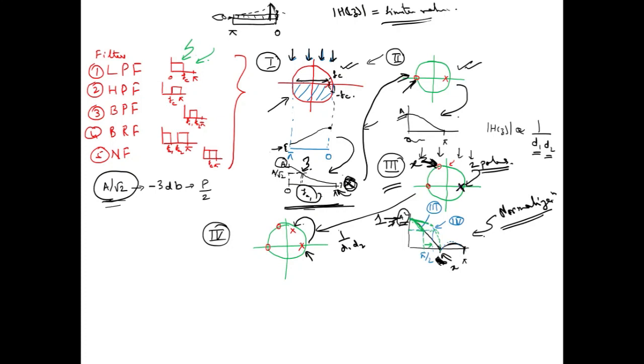So whatever output you get, there will be some frequency dependent distortion within the signal itself, but usually this happens in any of the filters and we accept that distortion. But when you are getting a very high roll off, like in the fourth case, what I have shown with this green response.